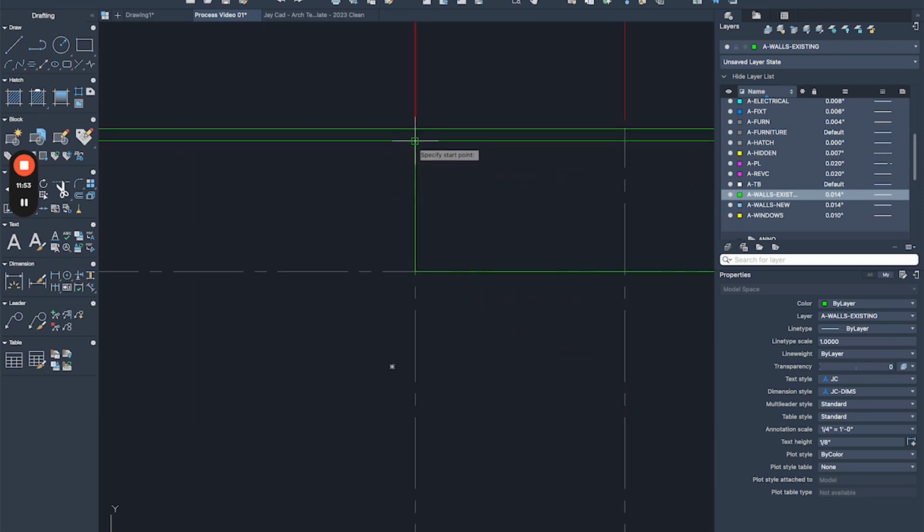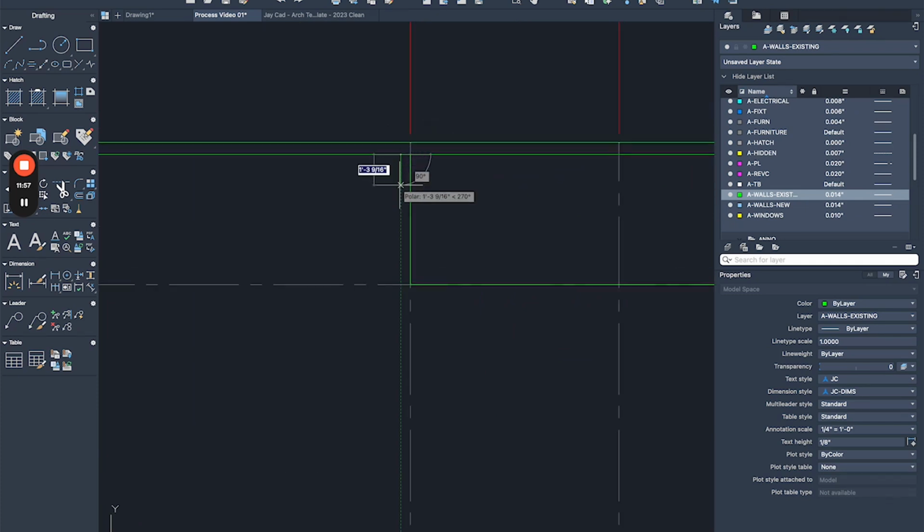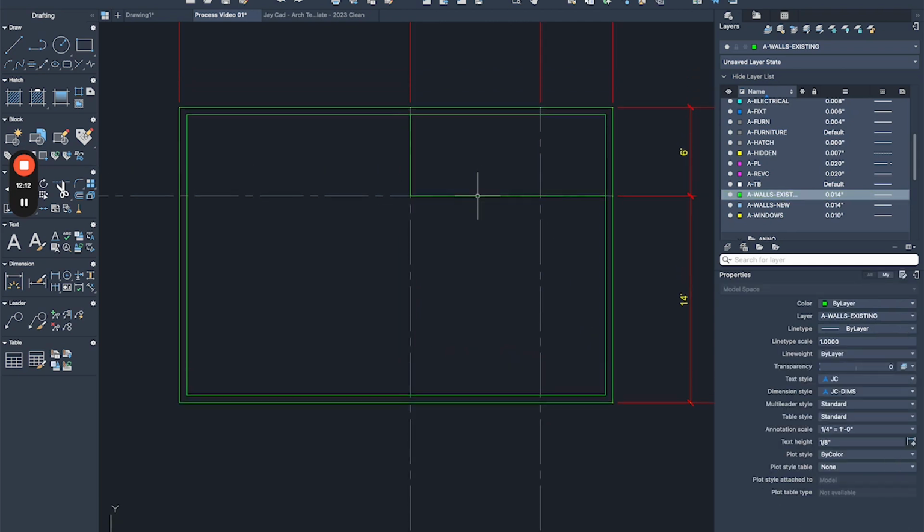I'm gonna do another polyline. I'm gonna go out by 5 inches for interior walls. I like to draw them that way. Some people like to be much more accurate and do 4.5 or 5.5 depending on finishes. I personally think you don't want to go this crazy when you're designing. You're trying to just get this going, right? I'd rather offset actually, just to make it easier for me.